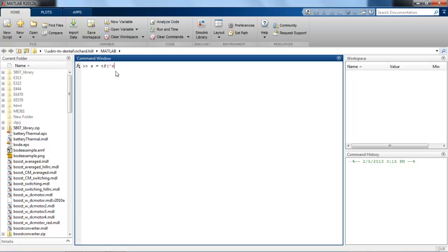The very first kind of command that we'll introduce is how to define the Laplace variable s, which MATLAB can recognize. And so once we've done that, we can multiply it, we can divide it, etc., in order to express various Laplace domain functions. Looking back to the previous example that we had, our function had a numerator of 3 times s plus 2, where multiplication in MATLAB is expressed with the asterisk.